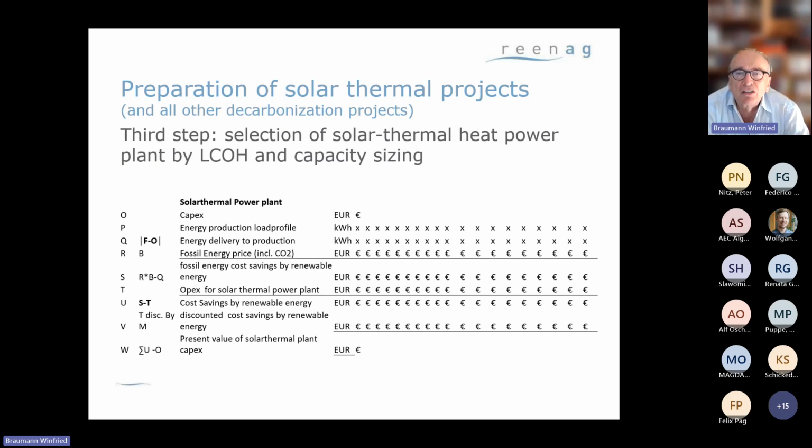The levelized cost of heat is the cost per kilowatt hour that characterizes a plant over its lifetime when using the entire generation capacity under local, environmental, climatic, etc. conditions. It is calculated by dividing the total of investment and financing cost plus OpEx by the kilowatt hours produced over the lifetime of the plant.